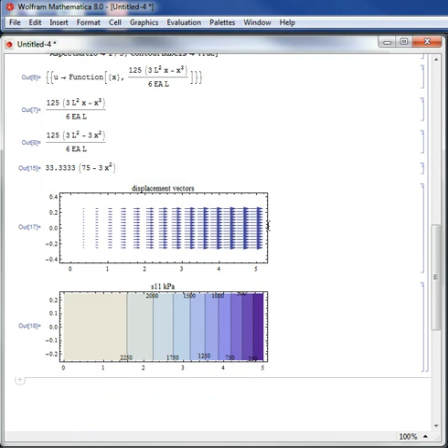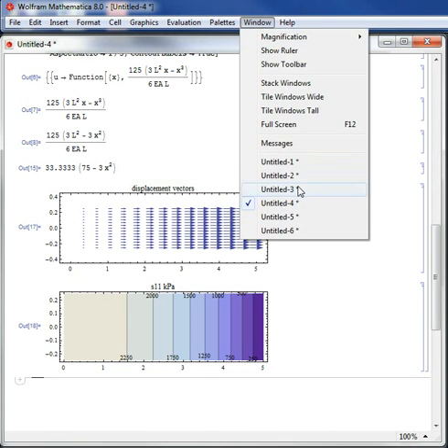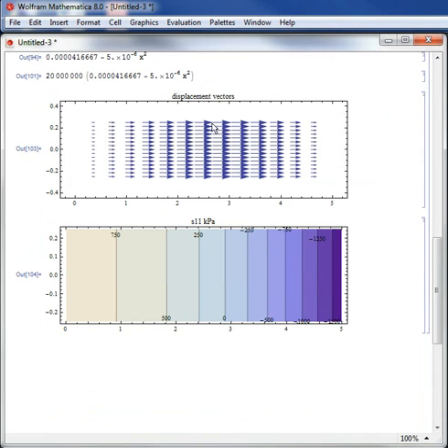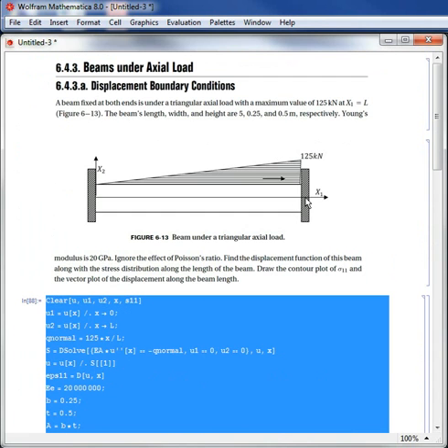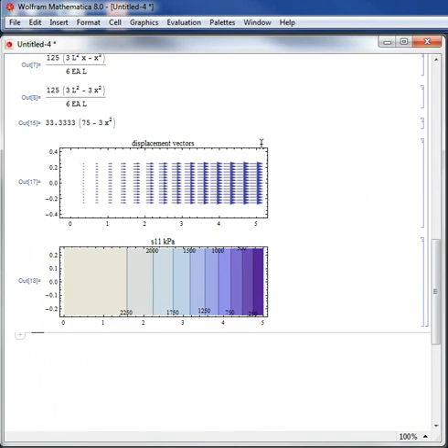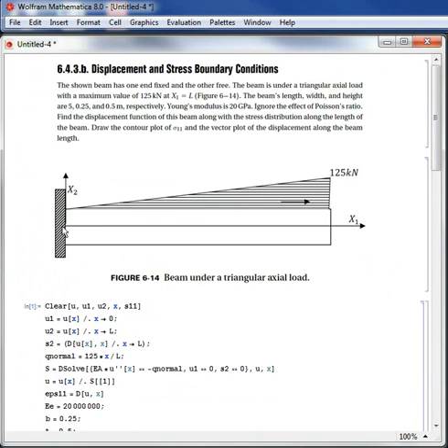The displacement here is much higher because the displacement here is 0 and the stress is tension everywhere. And compare with the previous problem, the displacement is only maximum in the middle. And it makes sense because there we restrained both ends, but in the second problem we restrained one end and allowed the other end to freely move.